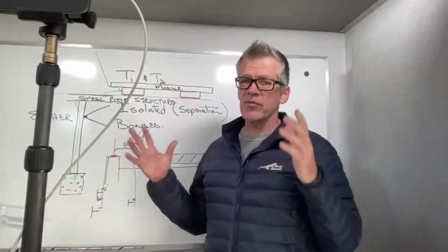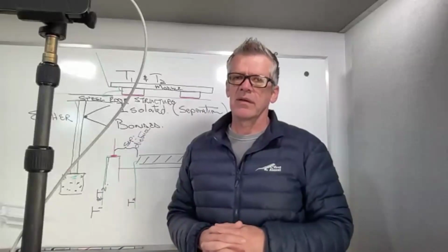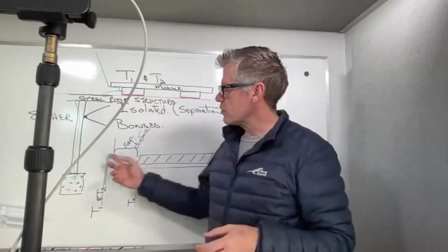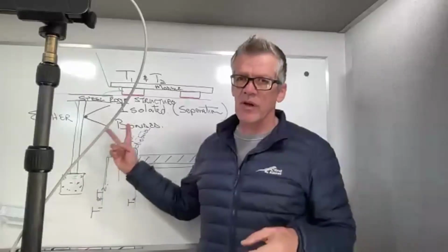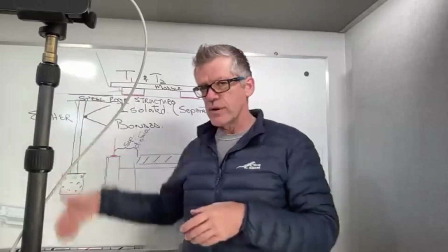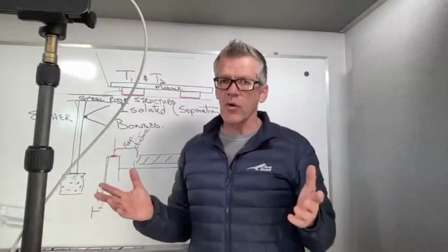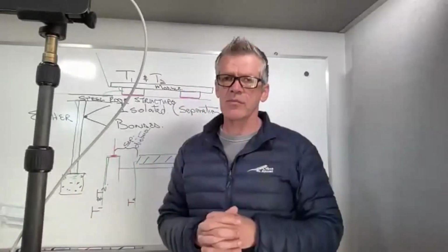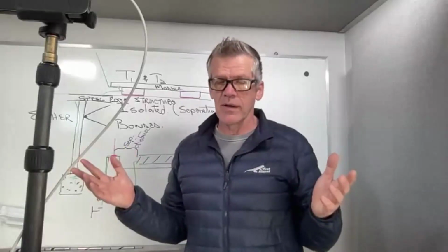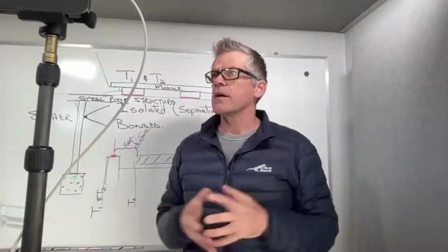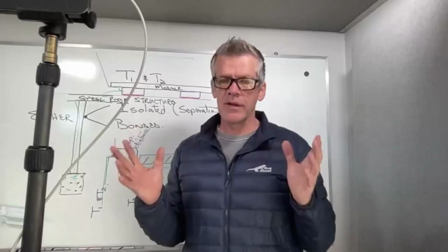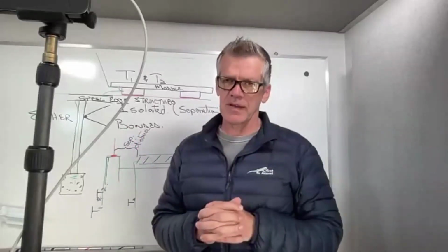Ralph, quickly, if you are expecting lightning, then according to 62305, you have to have at least 2 down conductors, one on this side of the house and one on the other side of the house. That is not how it's being done in South Africa at the moment, because that is not what the social media WhatsApp groups are busy discussing.